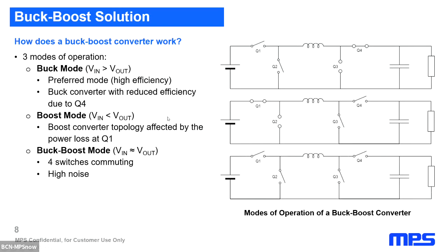The second mode of operation is the boost mode. In this case, Q1 is closed, Q2 is open, and Q3 and Q4 are switching. Then we obtain a boost converter, and the output voltage will be higher than the input voltage.